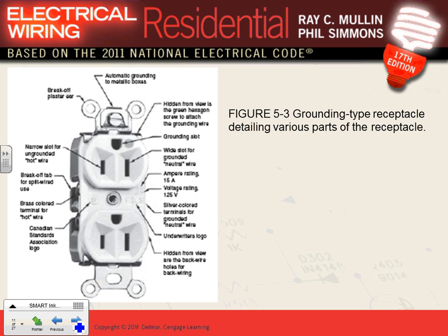Now, if you graduate from Dunwoody and you don't know the following, please ask me for a refund. I was teaching a safety training one time, and part of the safety training is they have to measure the voltage to ground between the neutral and the ground. And the guy asked me which slot is the ground; he was confused between the neutral and the hot on a receptacle like this. Okay, always remember that shoe-looking guy is your equipment grounding conductor, right?